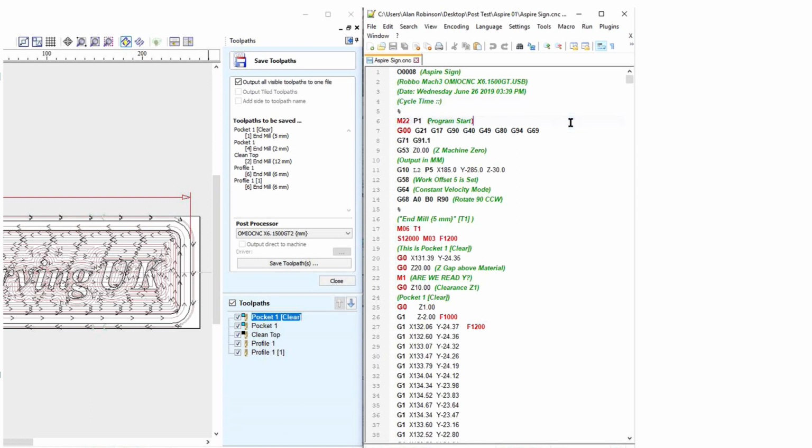Line 6 is irrelevant unless you have the custom screen set we are using, it can be ignored or removed from the post processor. It is used to automatically set the tools into the Mach 3 tool list. I will show you a manual way to do it later. Line 7 and 8, these are the default settings, they place the CNC into a safe mode.